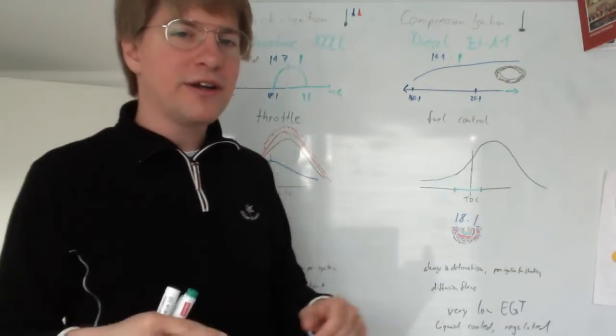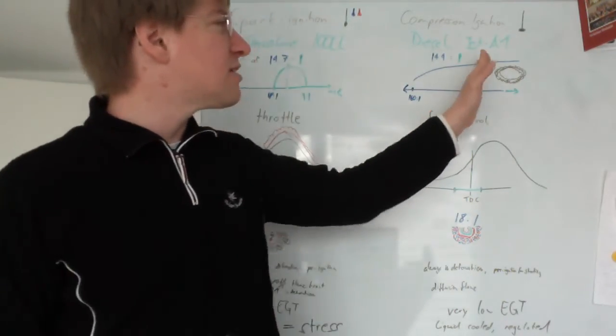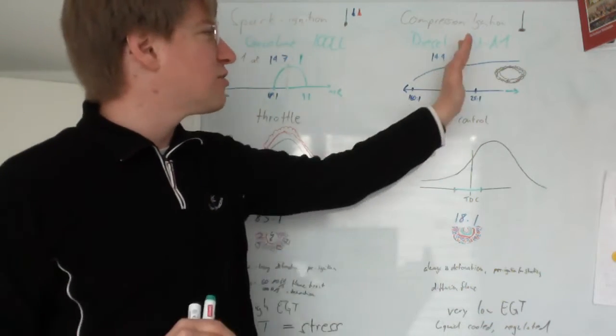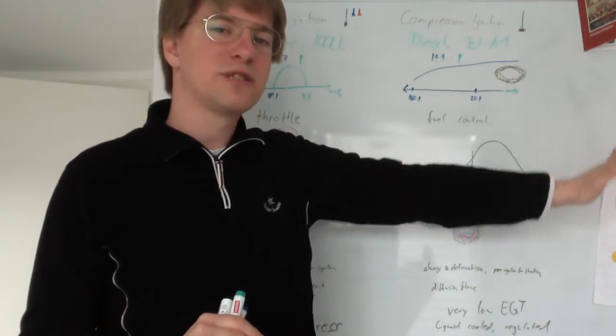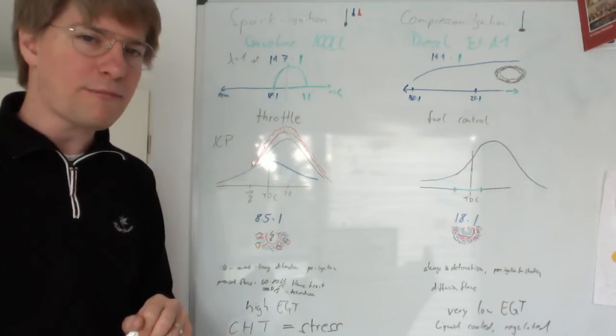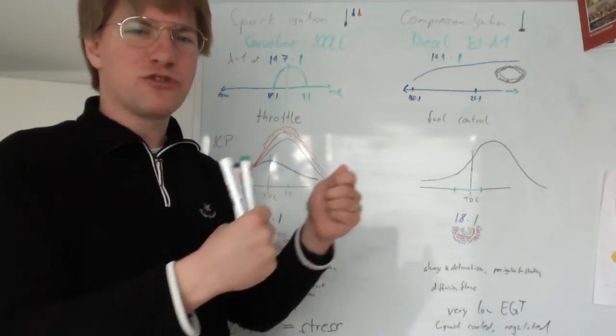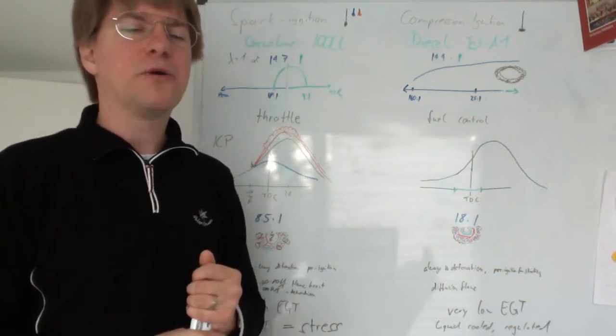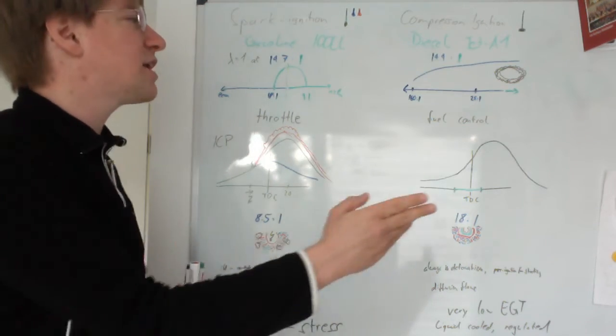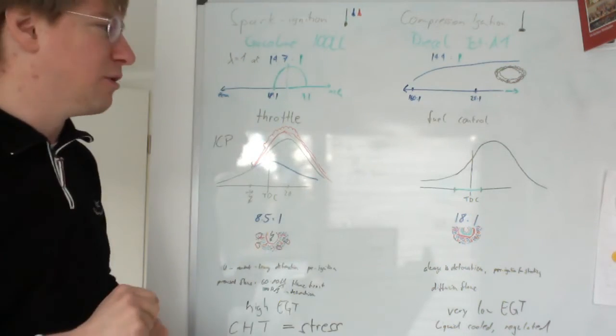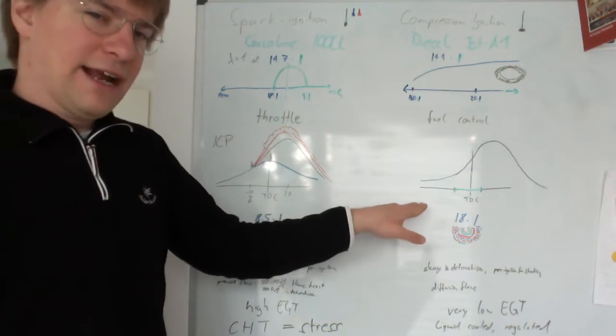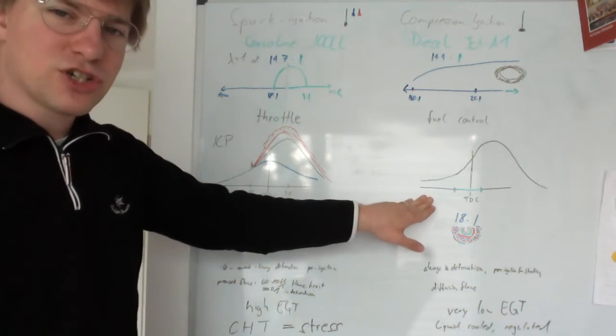And with modern electronically controlled diesels, of course, they have very precise control not to move into the smoke zone. Here they have mass airflow sensors measuring the precise amount of air going into the cylinders and then not injecting more fuel as to not get into the smoke zone. All right, let's look at what the combustion process looks like.